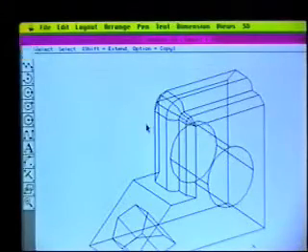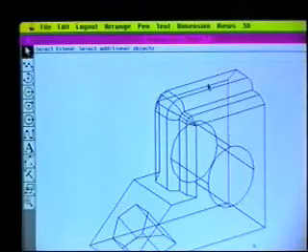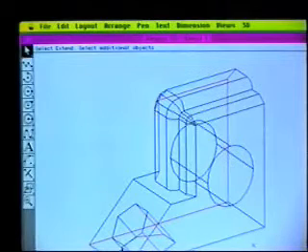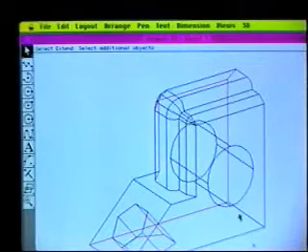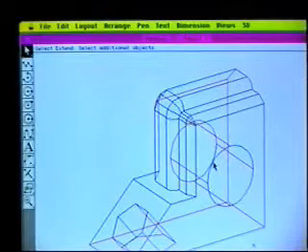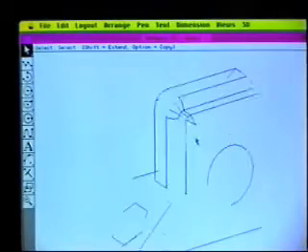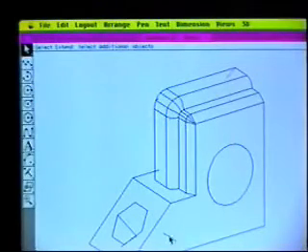So really the first step of this is just, we know there's a bunch of lines that I don't need. There's some lines hidden there, and there's lines back behind that I can just go through and select and delete them. So using the Shift key, I can click on many lines at once and make them all go away and make this process actually go very quickly. Now our hole is not quite big enough. We're not quite going to see through this, which is unfortunate, but that's the view that we've chosen, and I could have changed that, but that's the way it goes this time. So I will delete many of these lines, and I actually see that there's some here that I want to get rid of. And when I hit the delete key, those go away, and I've got a few stragglers.